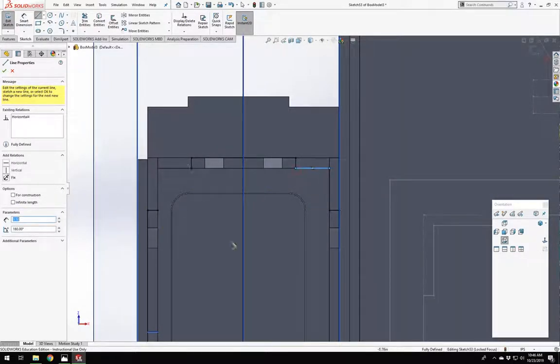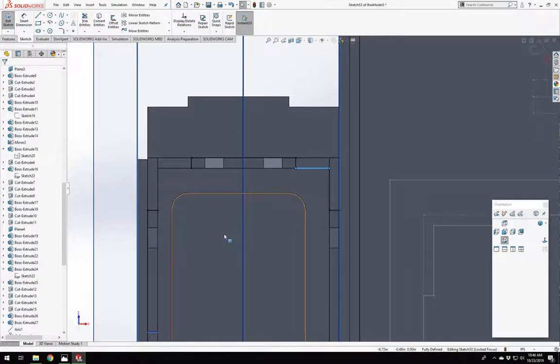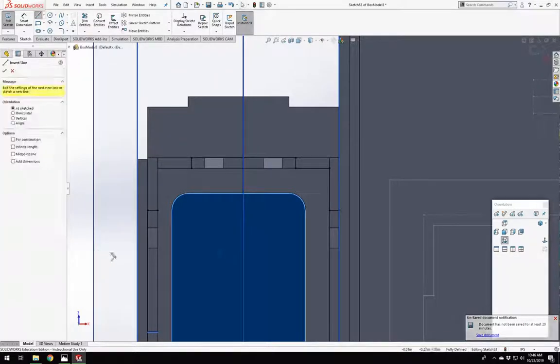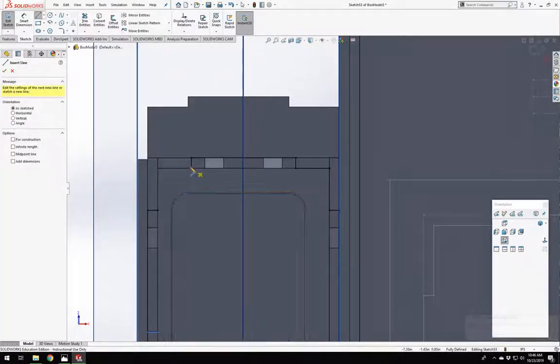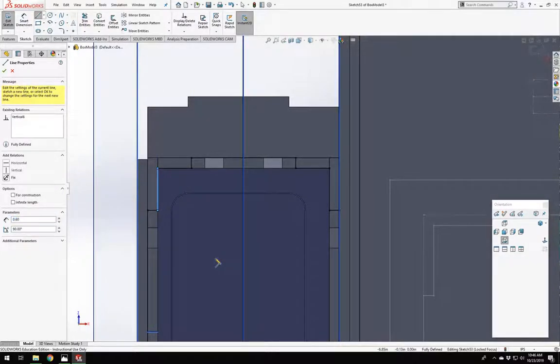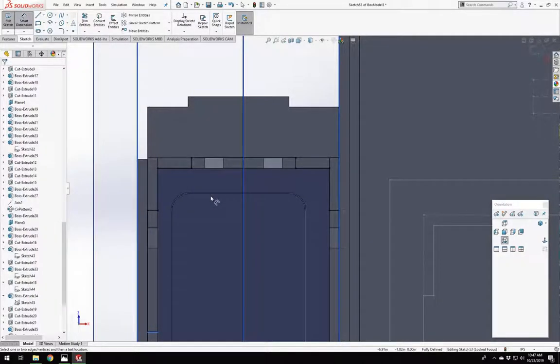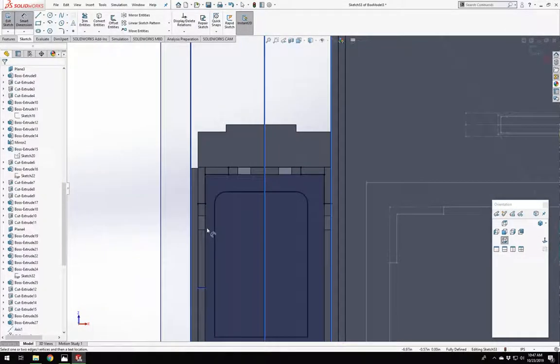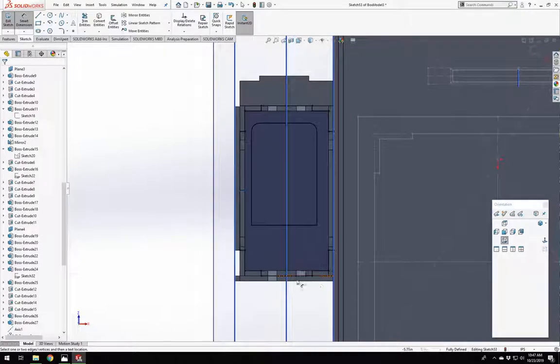What I'm doing there when I'm clicking and swiping is there's this quick select menu if you hold your right click. And so if you just sort of right click and move to the left, you end up with a line tool. You'll see me do that a lot to get to dimensioning, where I right click and I go up. But it's something you can actually do very quickly, and you can configure that toolbar as well.